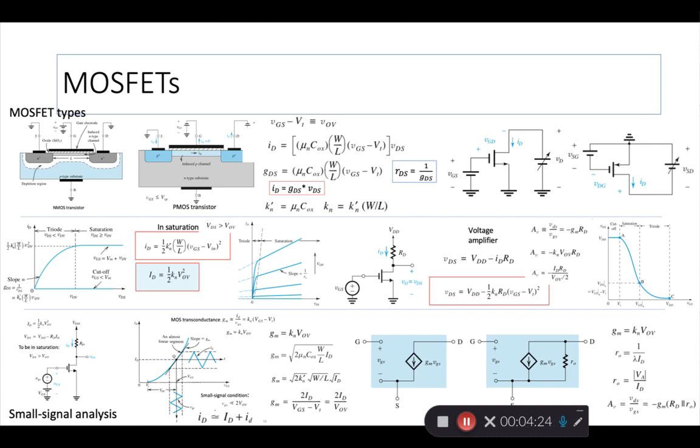So there are some new parameters or constants that get introduced when we start talking about MOSFET circuits or MOSFET behavior. First of all, there is this VT, right? That's called the threshold voltage, and it's different from the thermal voltage that we saw in BJTs, right? Don't confuse the two. That has a value about 26 millivolts. This is VT, and it comes in 2 forms, VTN or VTP.